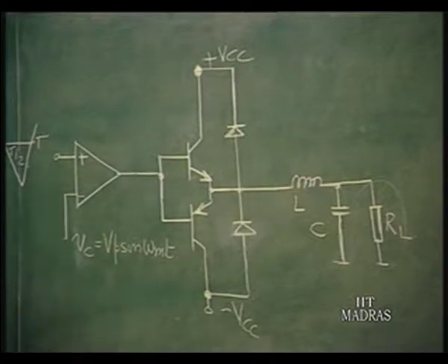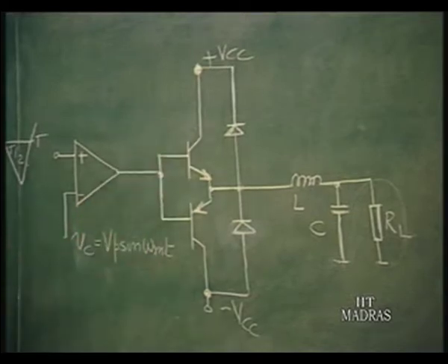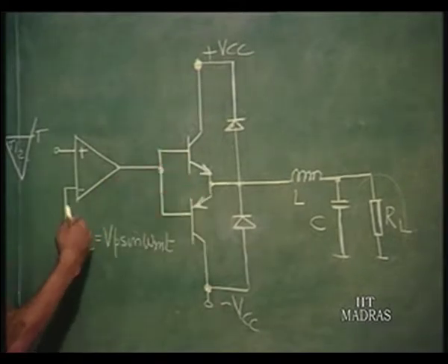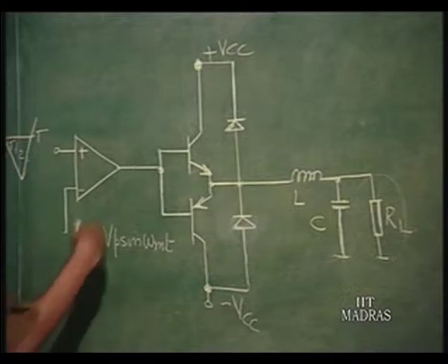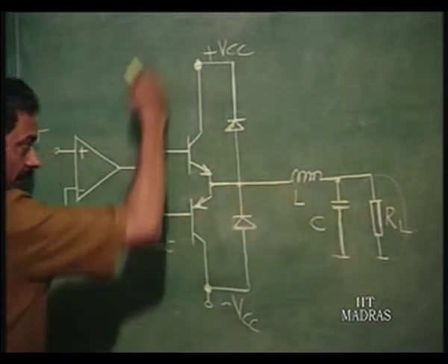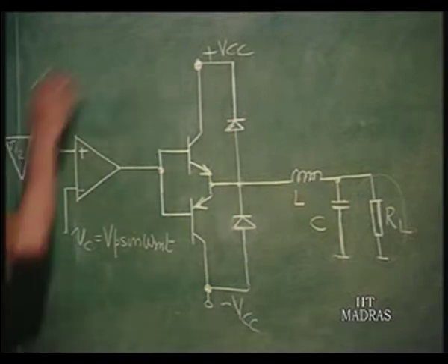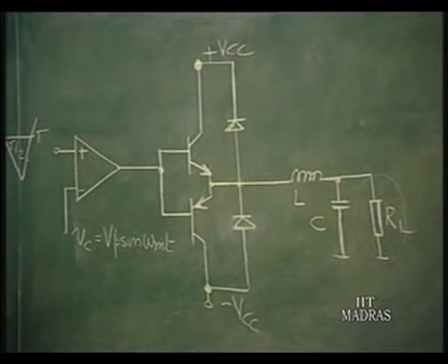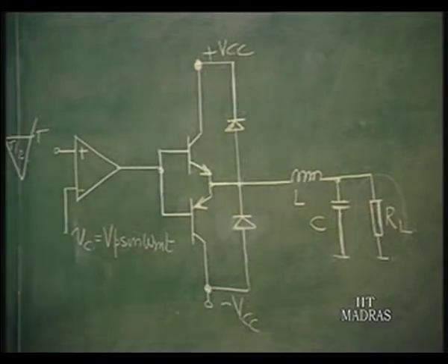So, if we say that the switches do not dissipate any power and L and C are ideal, then in this whole process of obtaining this power at the power amplification here, we have not spent any energy as far as this whole circuit is concerned, assuming that all these things consume very little power, okay, at the input side driver circuits, we can say that the efficiency is 100%.